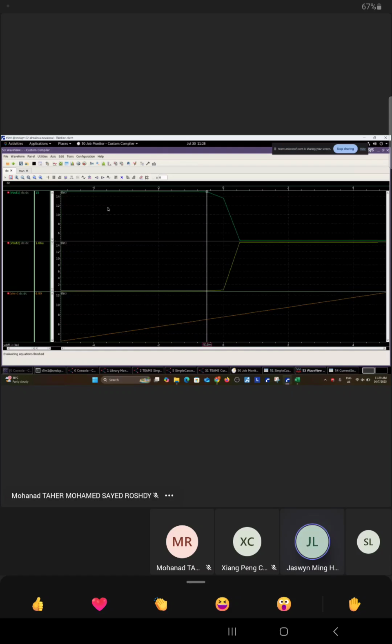At least just now 0.4 was the working range. Now it's still about that, right? Still the same. The gain is probably like 200 or 100 micro. Okay, one thing we can do now, instead of changing the tail current, is change the MOSFET connected to Vin plus and Vin minus. That's the first stage of the amplification.